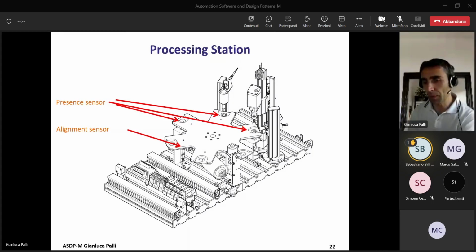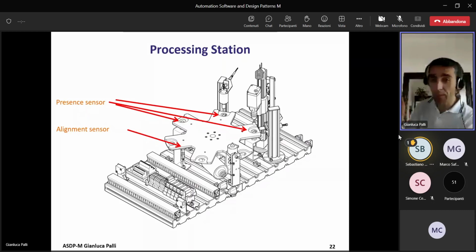You will realize that it is a bit tricky to stop the rotary table in the right position in the real hardware. You have to tune the mechanism. I give you a suggestion: probably use a filter that delays the signal the right amount to fix the rotary table in the right position.